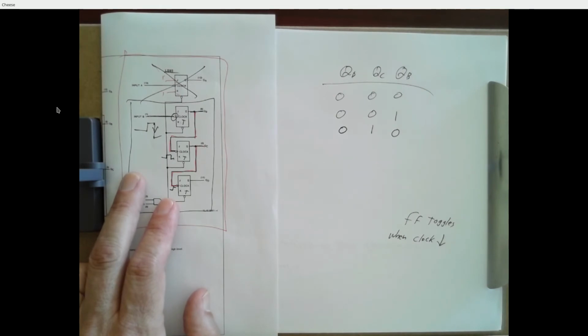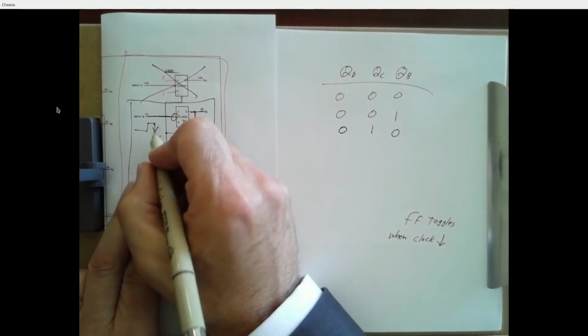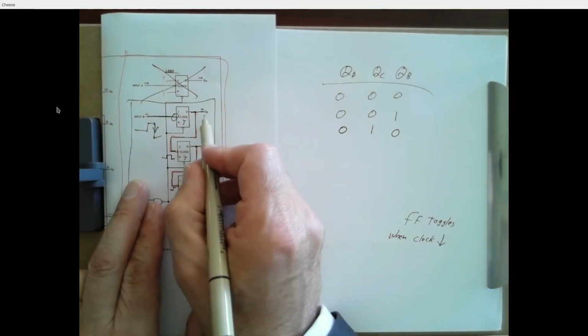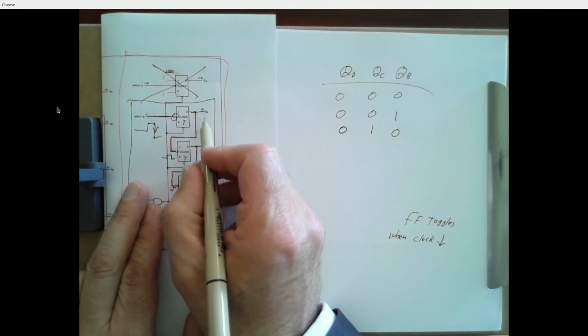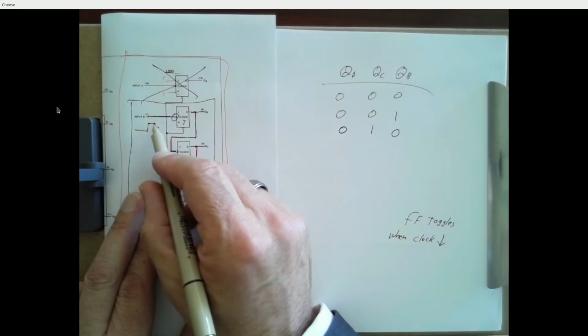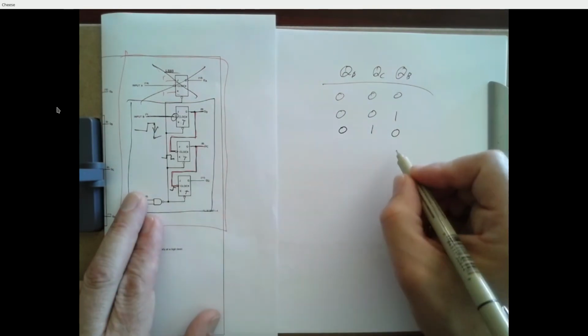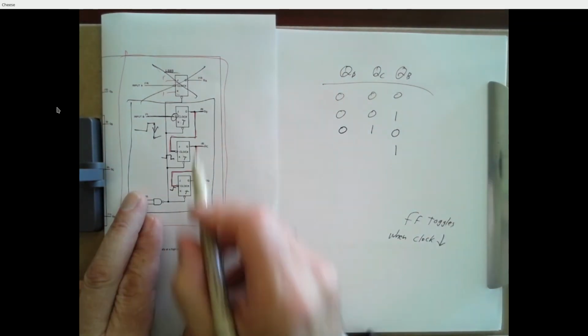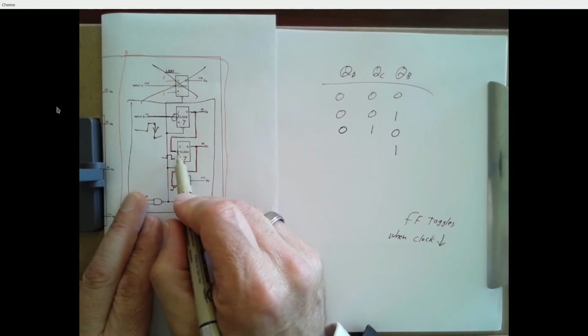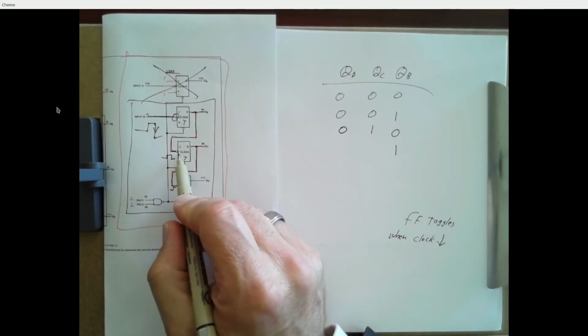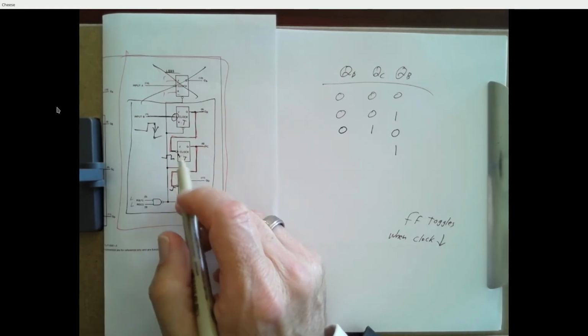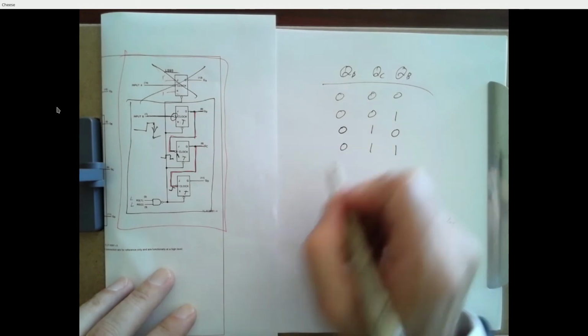And we can do this one more time. Input B drops. QB is going to toggle. Well, this is just going to keep repeating, right? Every time the input drops, QB is going to toggle. There's no two ways about that. So QB is going to become a 1, which again means this clock input on this flip-flop is going to go from 0 to 1, doesn't do anything. So this doesn't change, this doesn't change.